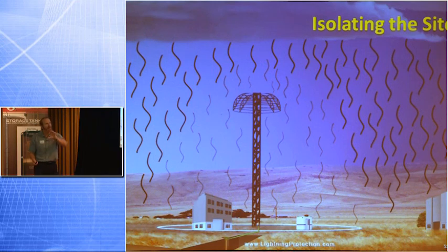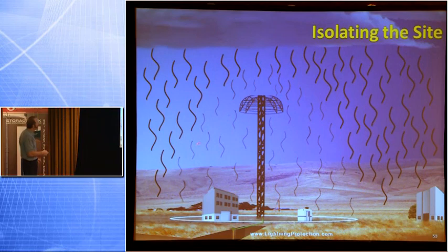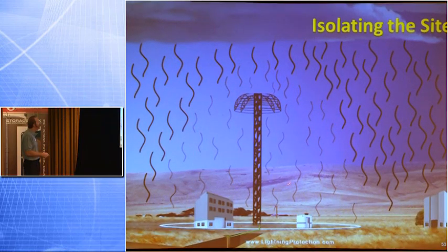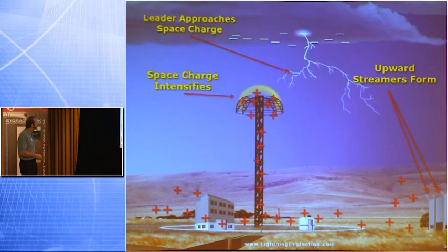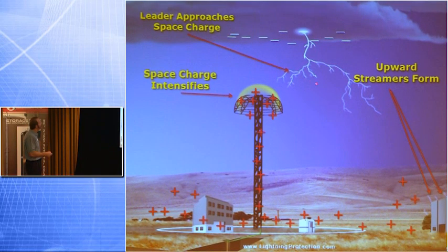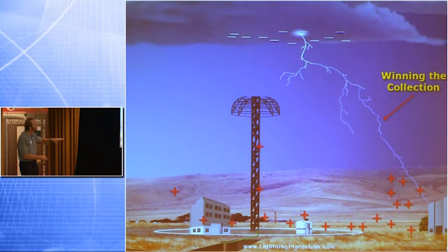30 kV, high potential. But because we've discharged the site slowly and continually by ionizing technology, multi-point ionizing technology, where we're constantly bleeding off that site slowly, methodically, continually during the course of the storm, we don't allow a very high electrostatic field around our zone. And by doing so, when that lightning occurs, we'll never generate the upward streamer. Why? You have to have 100 kV per meter. We're way below that. And we're slowing that leader down because it hits a space charge, it slows down, allowing the lightning to be collected off-site.